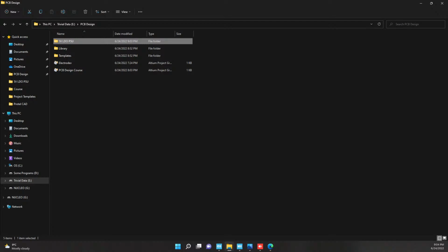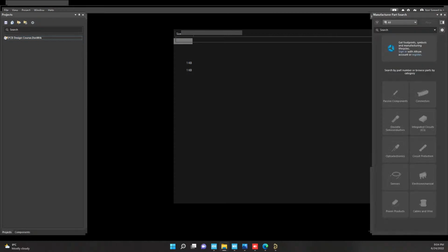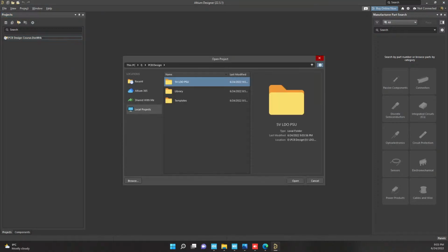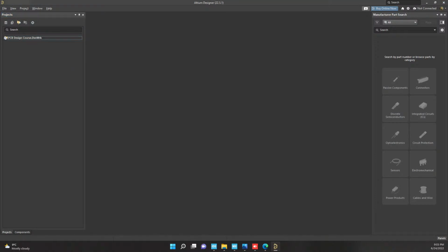I renamed the project and renamed the project folder. So normally, because the project's folder is different, Altium will lose the link to the project and therefore it will disappear from our project group. Which is fair, because now it's not the same folder anymore where the project is located, it's a different folder. So to re-add it, I'm just gonna say add existing project. I'm gonna select that, click over there, and voila. Here we have what we had previously.